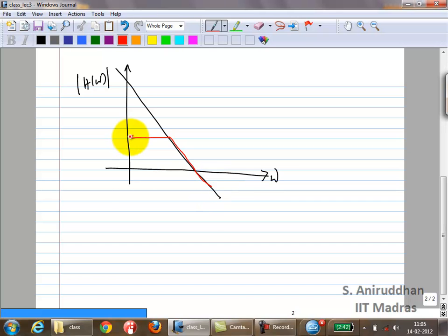With this gain being k, the low frequency gain being k. For the integrator itself, it was omega u, correct? Let's quickly find out what it will be for the closed loop case, right? We don't know that it's going to be the same as omega u.